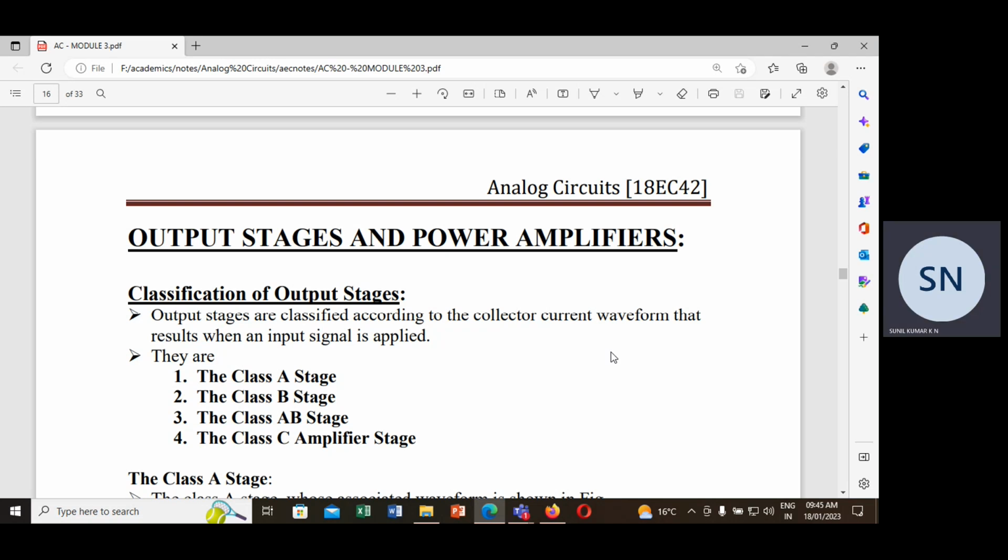So that is one of the drawbacks in negative feedback. So what is negative feedback? Even though it desensitizes the gain, the closed loop gain will always be less than the open loop gain. Correct? A over 1 plus A into beta.